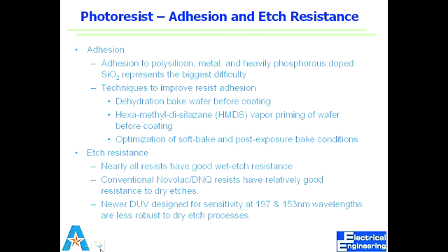So our soft bake has to be good. It shouldn't have any vapor. Those ovens are better which have air circulation, so they are continuously removing whatever is coming off the resist from the chamber. They continuously keep on removing water vapor or whatever comes out.